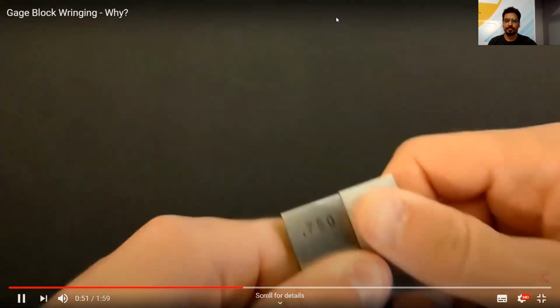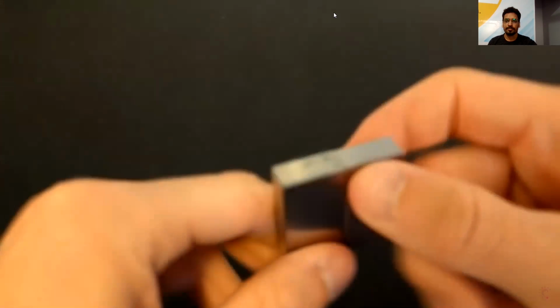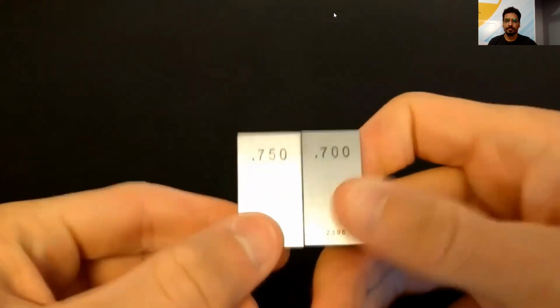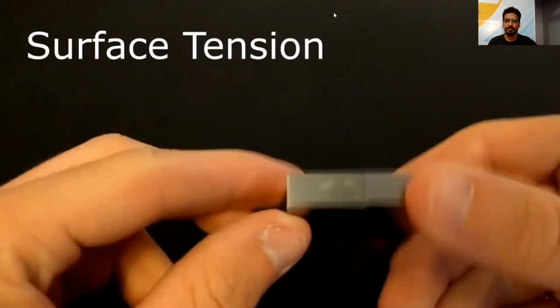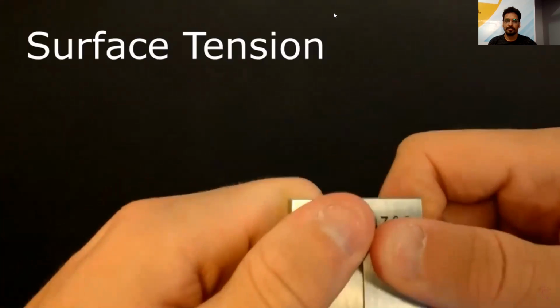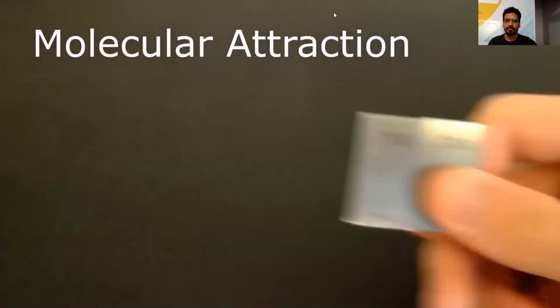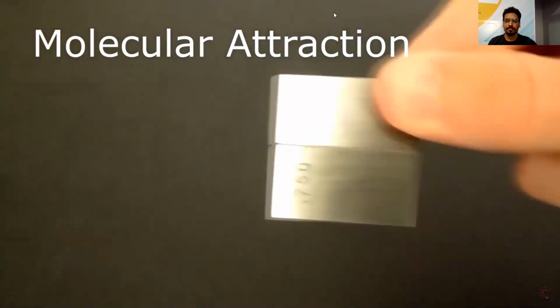First of all, because there is nearly no air between the smooth surfaces when pushed tightly together, the air pressure might push in on both blocks. Second of all, the surface tension from oil and water vapor on both blocks might hold them together. Finally, intermolecular forces might cause attraction since the surfaces are so smooth and molecules from the blocks are in such proximity. Gauge block ringing has been shown to work in a vacuum with clean blocks, and that is evidence that this is actually a factor. It's pretty cool.